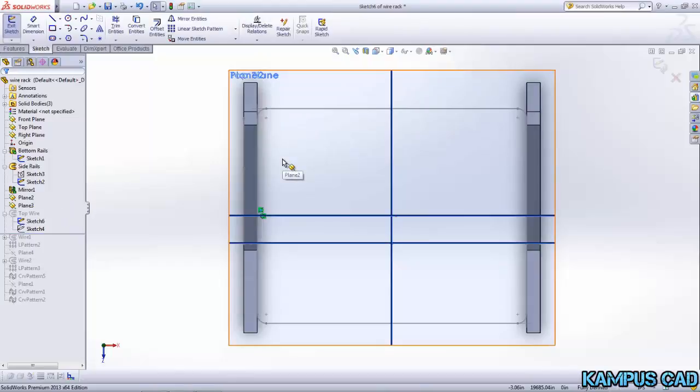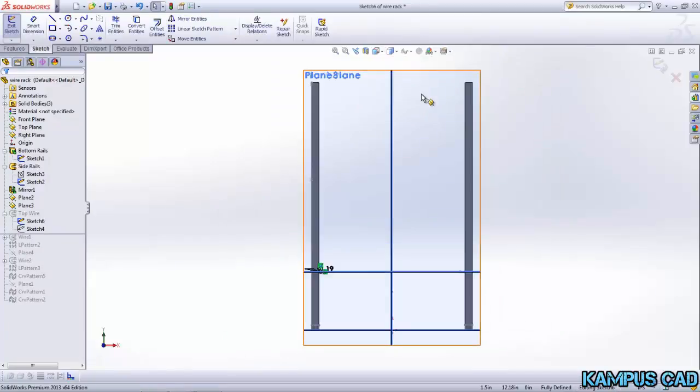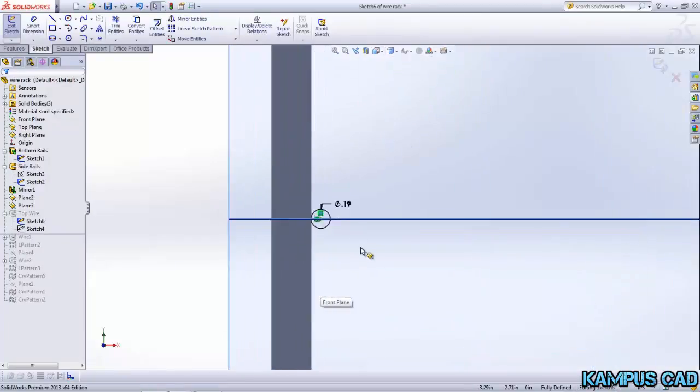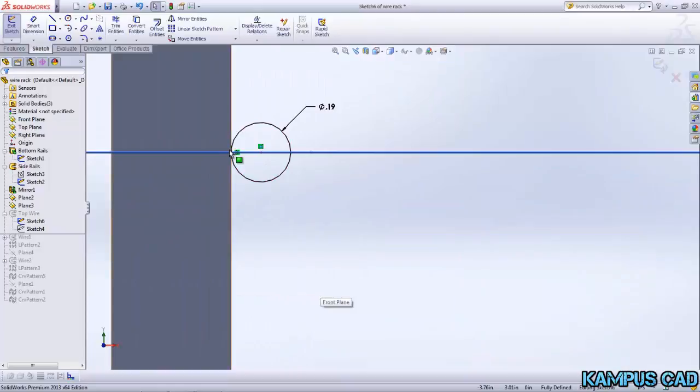But for the sketch, that'll be a little more important, because if I'm going to 3D print this, I want everything to be touching. So let's go to that. Just make sure you have a tangent constraint. I want this circle to be tangent to the edge, because if it's not, if you have a micro gap or something, it's just not going to be touching. So make sure you add a tangent constraint from my cross section to the side here.